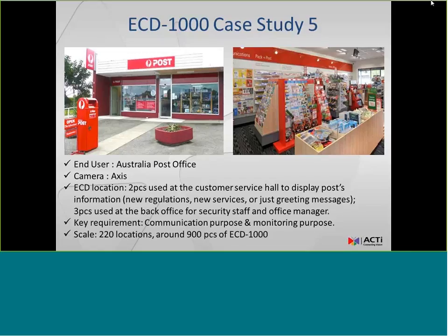In this case study 5, I would like to mention something very specific about Axis cameras. All the Axis cameras, before being added to a device via ONVIF, have to have the ONVIF profile enabled. For this, you have to go to the Axis camera firmware and open an ONVIF account for the Axis camera. After the account is opened, the ONVIF profile will be enabled on the Axis camera, and after that it can be added in the ECD 1000. This is not only about ECD 1000, this is talking about all Axis cameras that are being added to ONVIF devices.